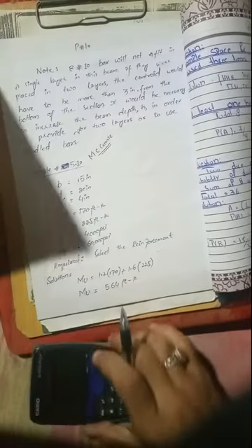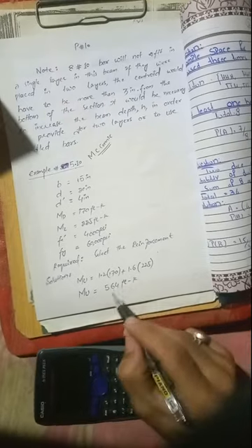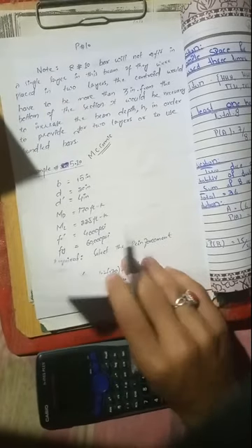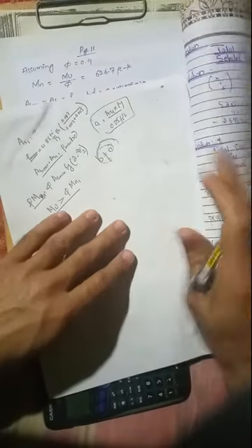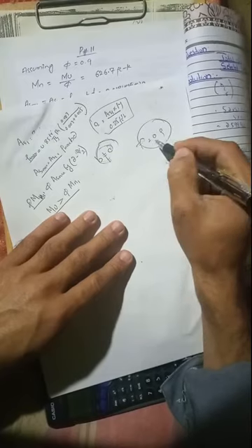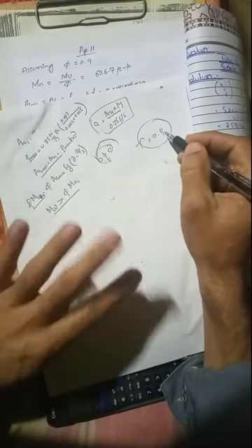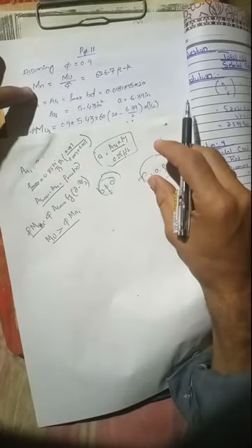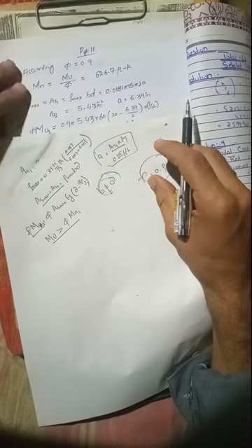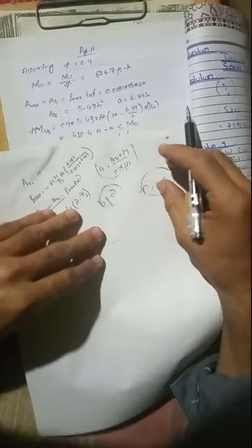So let's start the example. We calculate the Mu value as usual. We got the value of 564 feet-kip. Now let's say we are assuming phi value is 0.9. This is the first assumption, remember. In later stages we will check whether the phi value 0.9 is okay or not. We will find Mn, the nominal moment capacity. We don't need it at this stage, but let's say we calculate Mn equal to 626.7 feet-kip.